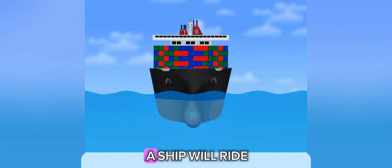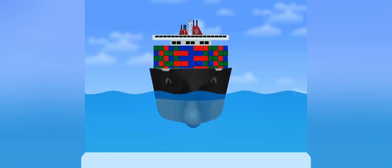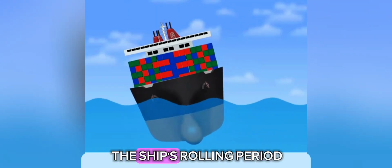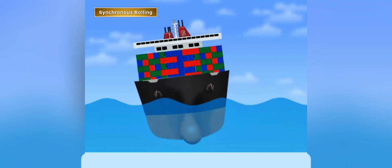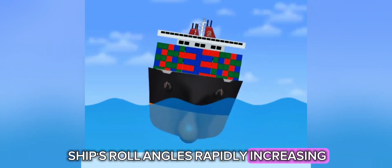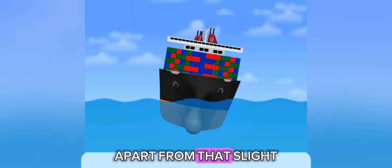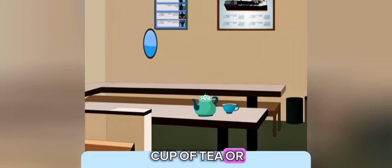Most of the time, a ship will ride the waves, softly rolling from side to side. Sometimes, when the wave period is the same as the ship's rolling period, we have what is called synchronous rolling. This results in the ship's roll angles rapidly increasing and may even lead to the capsizing of the vessel. Apart from that, slight rolling is not an issue on these ships, and you'd expect a cup of tea or water to stay on a table when you are on a ship.